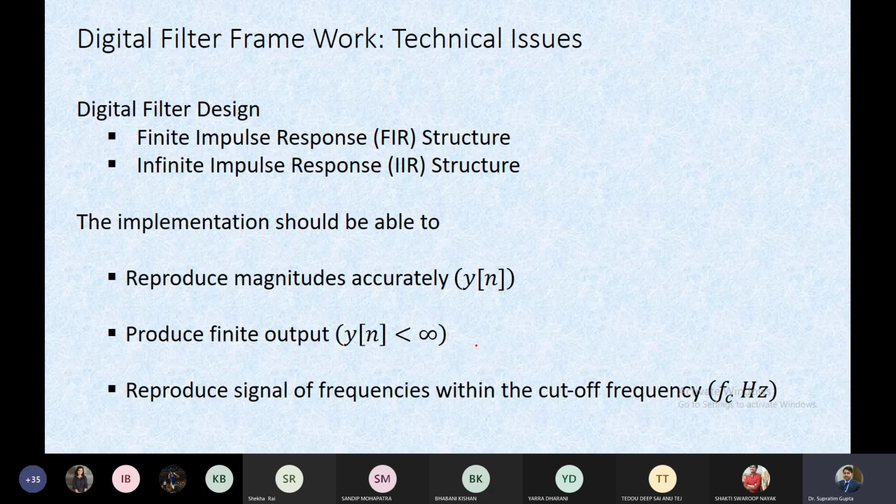One of the sources in the digital case is the precision of the sample representation. As I said, the data is represented by the ADC. For example, for ADC 0808, it has 8 lines. It means it divides the whole range of the signal into 256 levels, and so we have a minimum resolution of the signal below which we cannot get the signal value. In that situation we often have to truncate, that is, quantize. So the ADC is not only quantizing the time axis but also the value or magnitude axis.